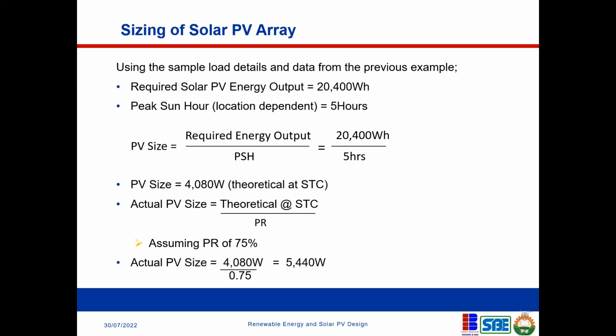So every year, solar PV degrades. By standard, I would say it's 0.5%. Anyone that degrades more than 0.5% might not be top quality in the market. The technical documents of the PV model will give you all of these details. It's very clear. We should check with the manufacturer.